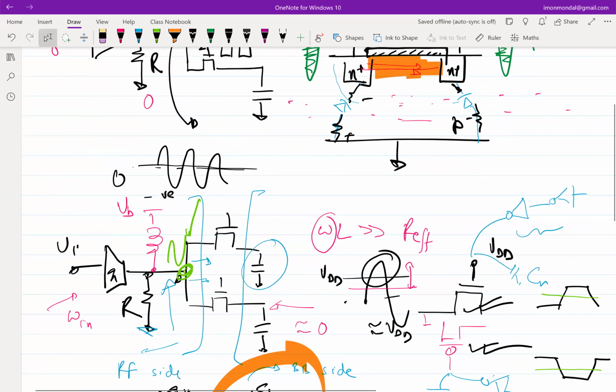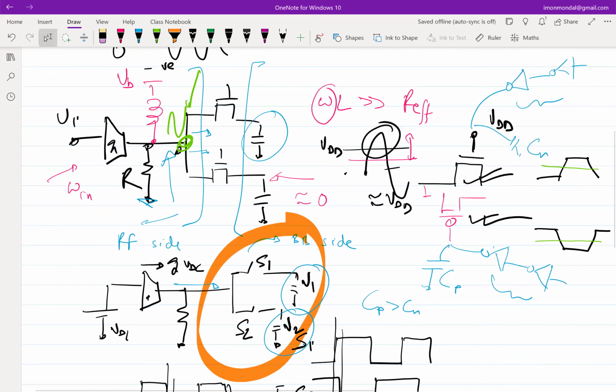The fault is the problem of those external circuits which are driving these switches, which is true. But the fault of the PMOS is that it forces those sizes to be higher. Also PMOS and NMOS do not track each other. Their threshold voltages do not track each other. If everything was NMOS, say one NMOS has a threshold voltage of 400 millivolts, with a fair amount of accuracy you can predict that the next identically laid out and sized NMOS will also have a threshold voltage of 400.